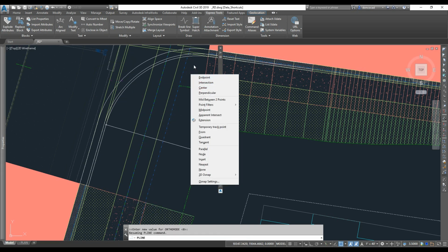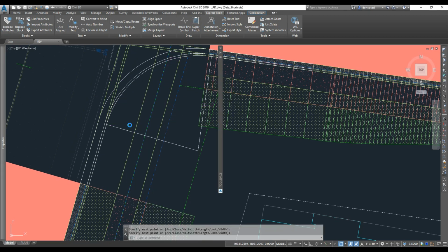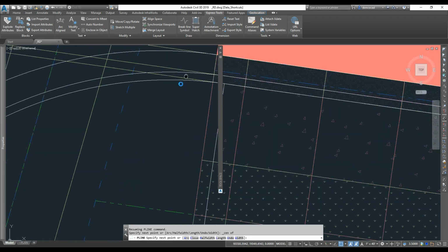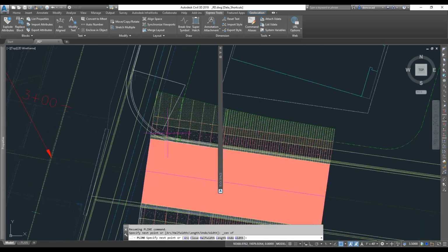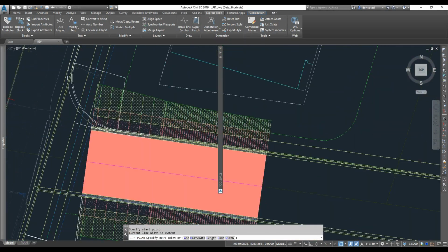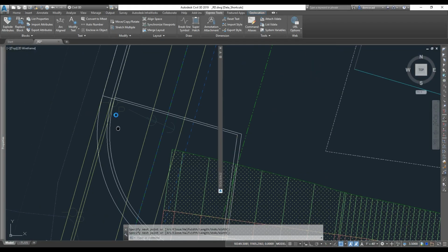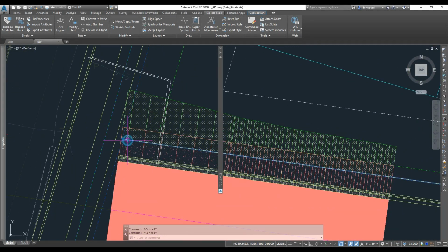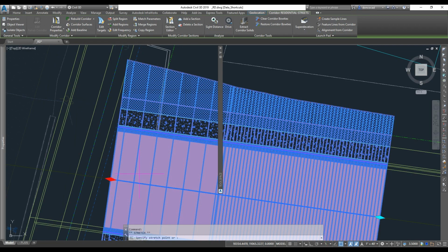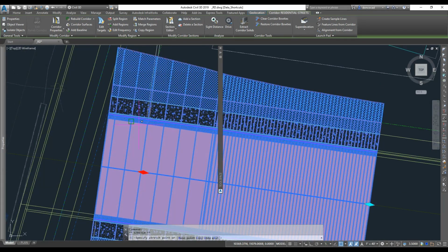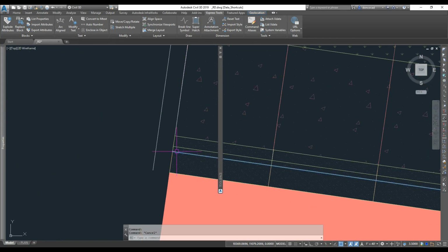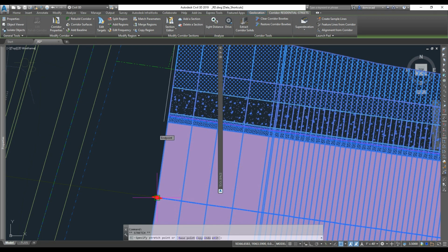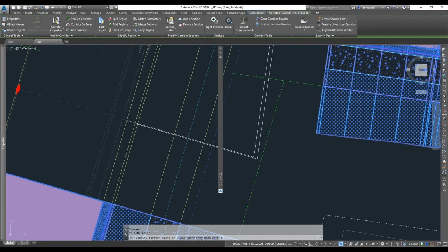Eventually, I'm going to again draw my geometry up here, and the problem here is that we have 2 different widths of curbs so far, unless we get the city to back down on one of them. But yeah, for one street it's one width, the other is the other. So you're going to have 2 slightly different radiuses there. But I'm just going to go ahead and kind of trim these back out to where the intersections will be, and then eventually come back in and use the intersection tools later on after dinking around with some sidewalk modeling experiments.